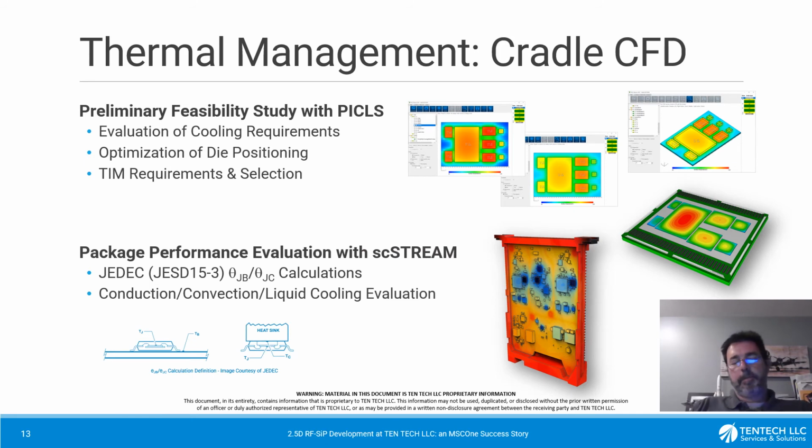Similarly, the thermal management itself. So thermal management becomes important almost the first day of the design. Can we even cool this thing? How much cooling do we need? Again, those products can range from 100 to 300 watts, sometimes 400 watts, depending on what FPGA and what die we use. So we need to quickly evaluate what we're going to need to cool this down.